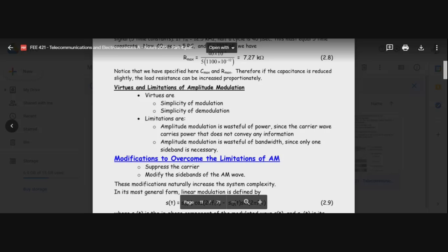What you pay for that is that the demodulation will become more complicated. But at least you can carry more message when you suppress the carrier, because the power that was consumed in the carrier is now available for carrying the message, and then you pay for it by having a more complicated demodulation. You'll see that later.